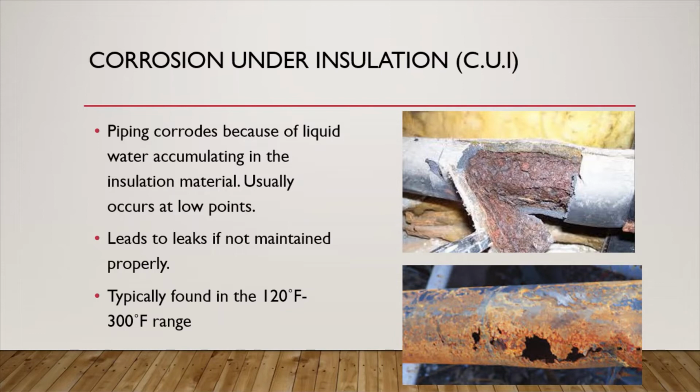CUI is only really found in the range of 120 to 300 Fahrenheit, and it accounts for the majority percentage of a maintenance budget, so it's a big problem in the industry and can lead to accidents and explosions, like the one at the Richmond refinery fire.